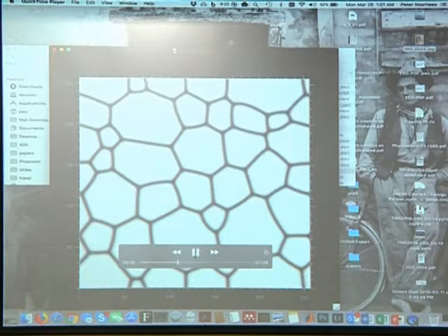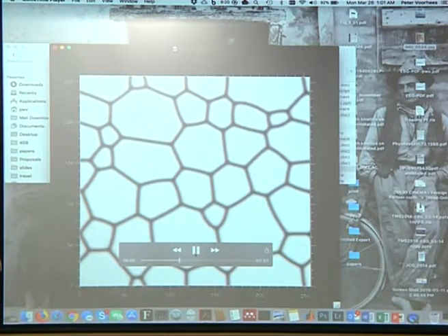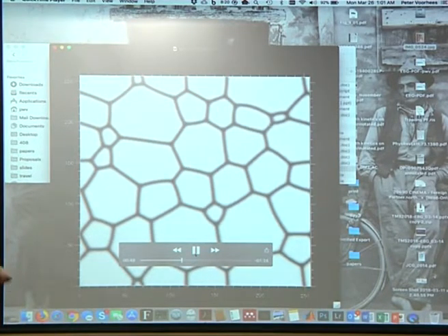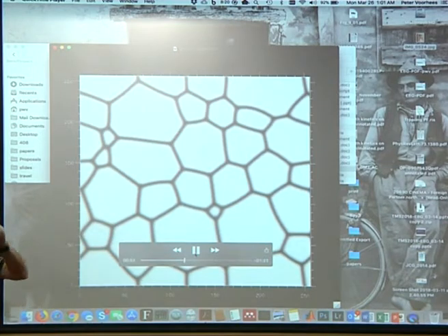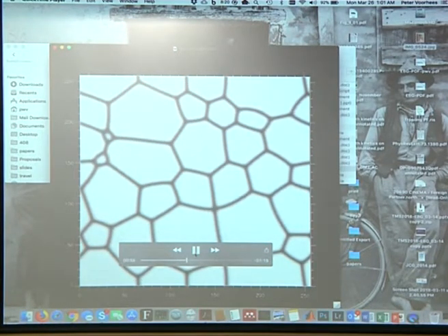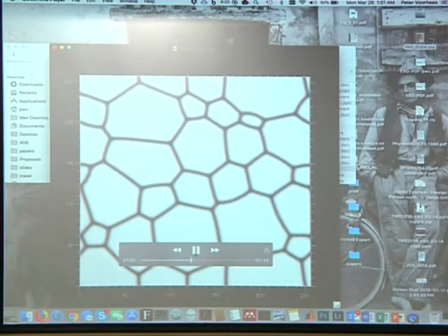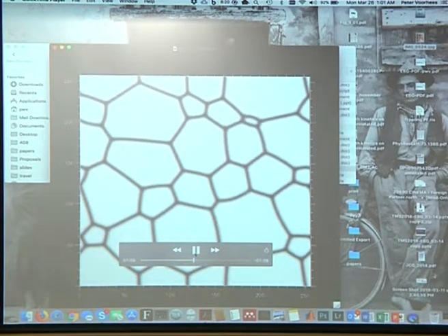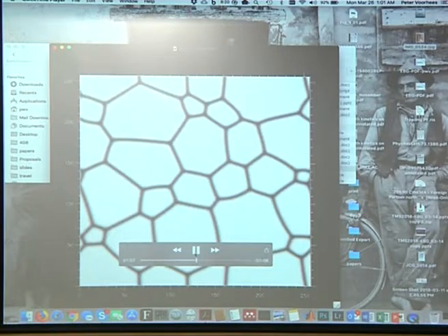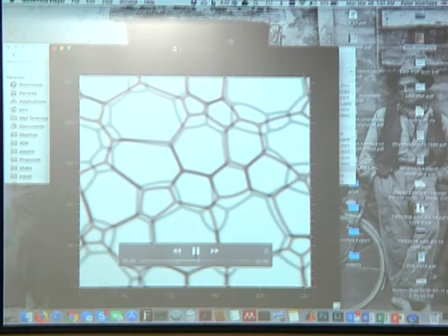I want to point out, maybe this will pop up near the end, but one of the problems with these models that you should be aware of if you try to actually use them is that, remember, you have a vector order parameter with zeros for all the grains and 1 for the grain of interest. And so if you have n grains, you need n Allen-Cahn equations. And if you want to do 1,000 grains or 10,000 grains, you need 10,000 Allen-Cahn equations, which can get pretty computationally challenging. And so what people do is that they don't use 10,000, they use 100.